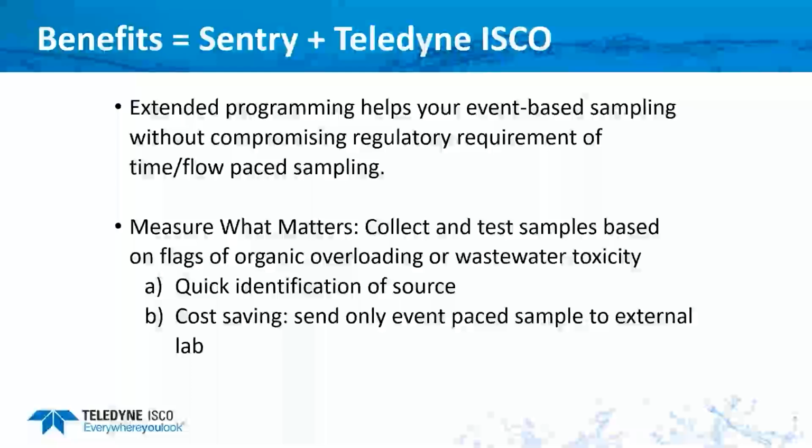At the same time, it can also save cost, because many times a third party is involved. Your regulatory sampling you can do in your local labs available at the facility. You can continue doing that, record the reading, and report it to the EPA or DEQs, wherever it is. But when it is event-based sampling, sometimes because a third party is involved, they may ask you to use a third-party lab. Those samples are expensive at a third-party lab, but you don't have to send every sample to a third-party lab.